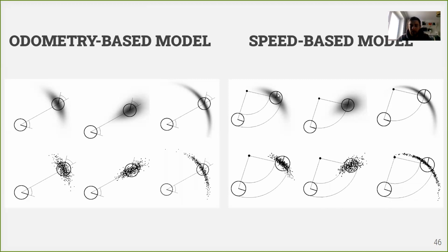And the second part of the equation of Bayesian estimation is about how to make our estimation more precise on the next step. Because we have not only motion, we also have sensors placed on the robot, some lidars or cameras. Using these sensors, we can become more sure where we are. This distribution should have less variance. It will be more condensed after the second, correction part of Bayesian estimation, and this is what we will use for the next step.